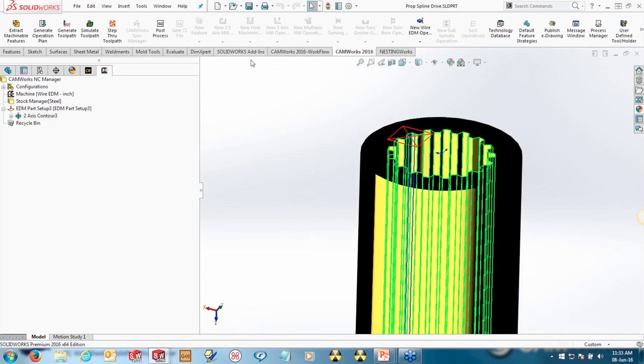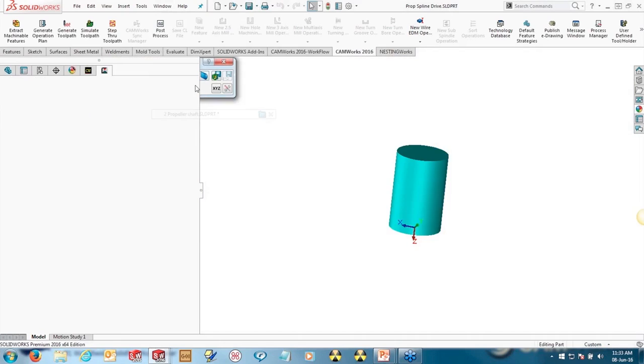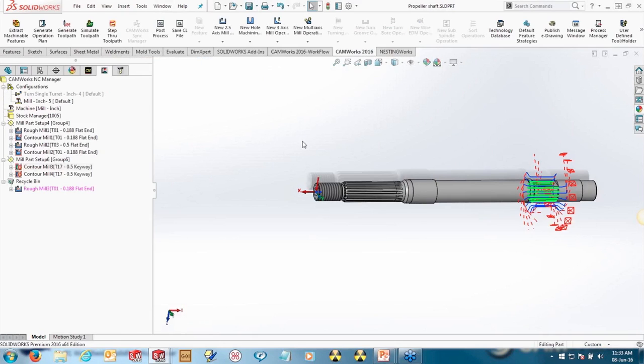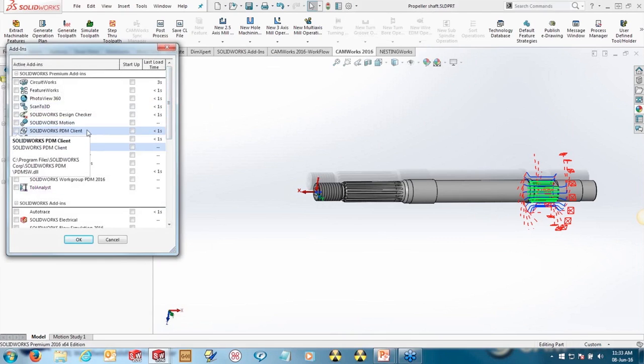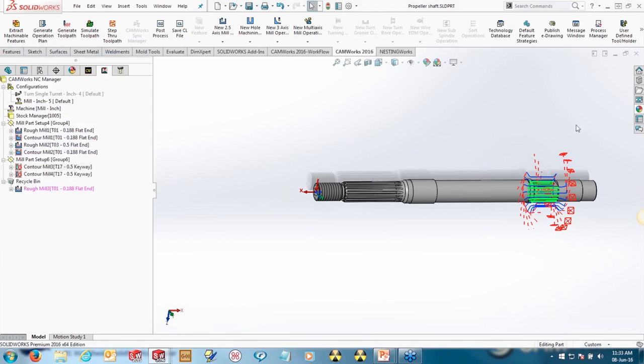Now if we just save these, go back to say the prop shaft over here, what happens if then the designer says, oh, we made a mistake, or we need to bump up the revision on this here? Maybe it goes through a PDM workflow. If you've got your PDM system set up, basically using the SOLIDWORKS PDM client for Enterprise PDM, maybe you go through a different state. You can actually enable the options over here, check the file back in, maybe switch the state on it to put it through a different workflow loop, go through ECO, all that process and things like that.